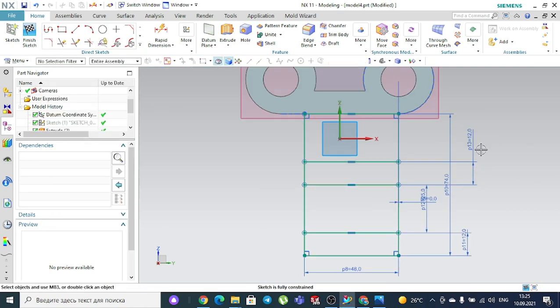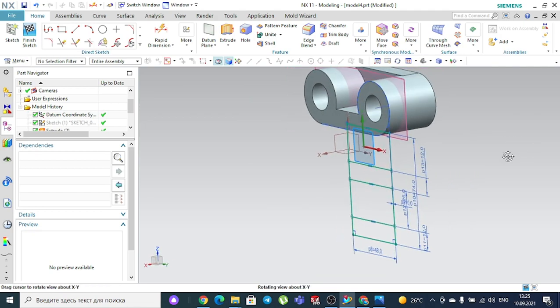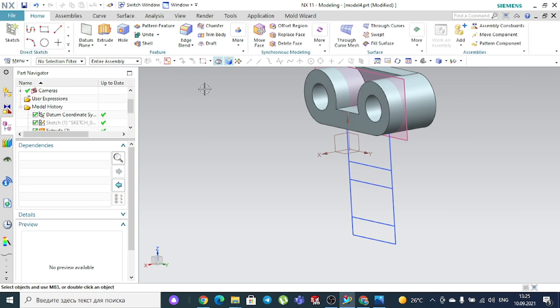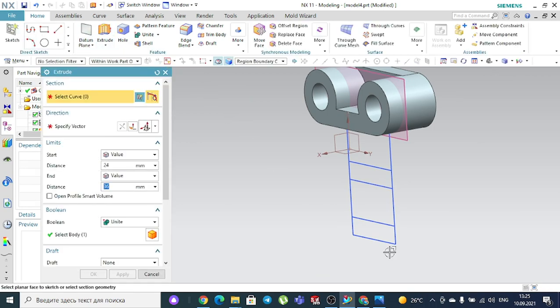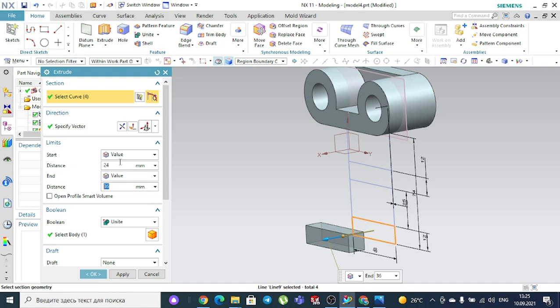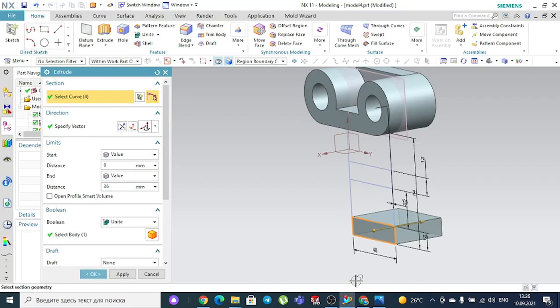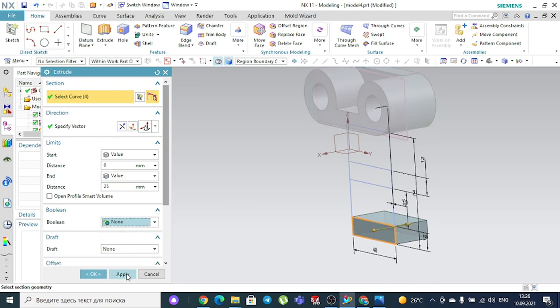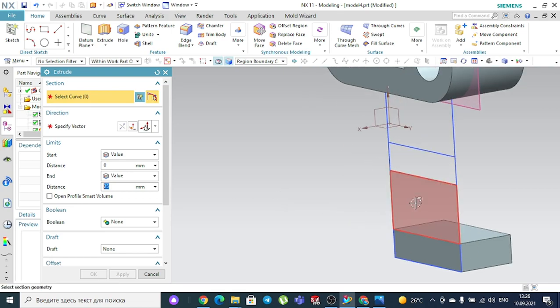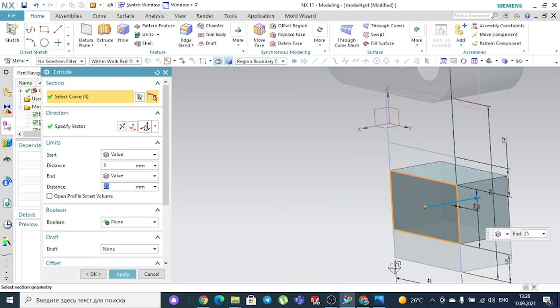So now I can extrude it using the boundary again as usual. In order to finish it, extrude it step by step. I will extrude it, for example this one, and firstly let's make it 0 starting point and reverse direction, and let's see, here is the 25, lower part is the 20, here at the end value 25, so here the known should be okay, apply, and the next region, this one is the reverse direction.